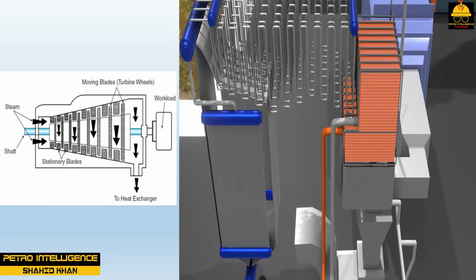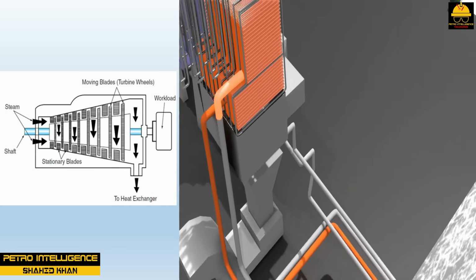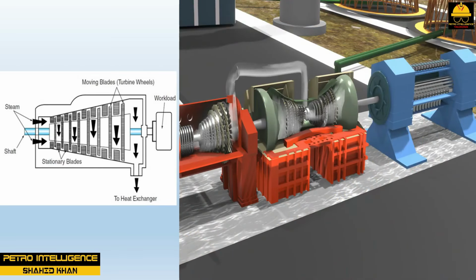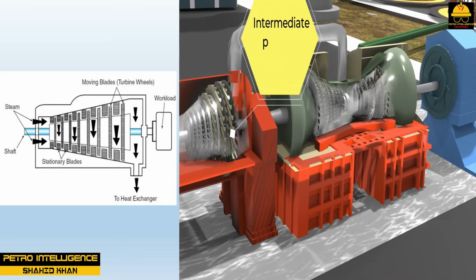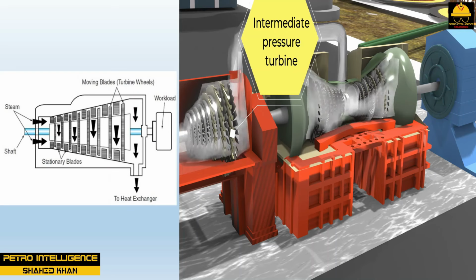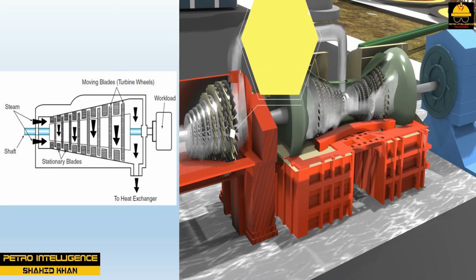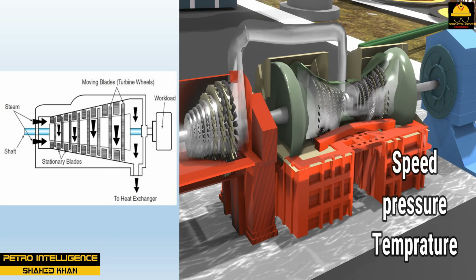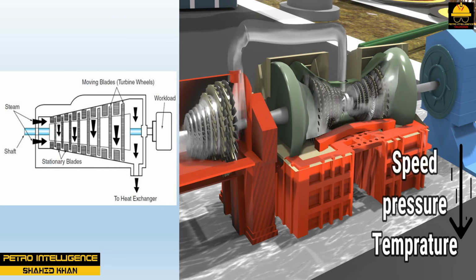A multi-stage steam turbine is considered to be one of the world's most powerful engines. Modern turbine technology includes 50 or more stages linked along a horizontal shaft. Each stage consists of a set of moving and stationary blades. The curved blades of each stage are designed so that the spaces between the blades act as nozzles and increase steam velocity.